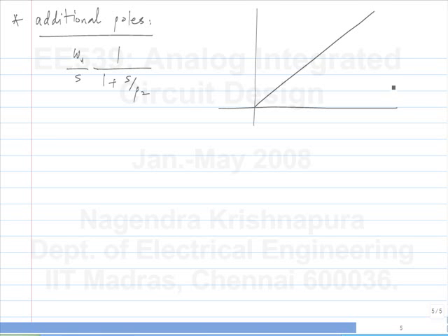Okay. So, this is versus T, and I have an input, let us say VDC, or I think I used Vx the last time. If I put an input of Vx, I have a ramp of rate omega u times Vx. Now, this was for an ideal integrator, if I just had a transfer function omega u by s. Now, I also have an additional pole in the integrator. What am I going to get as the output?